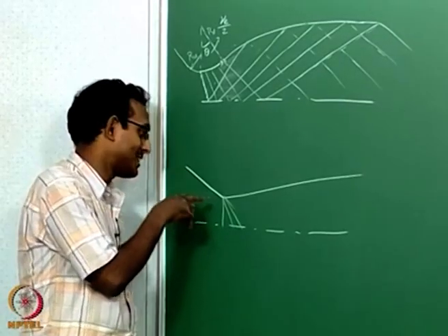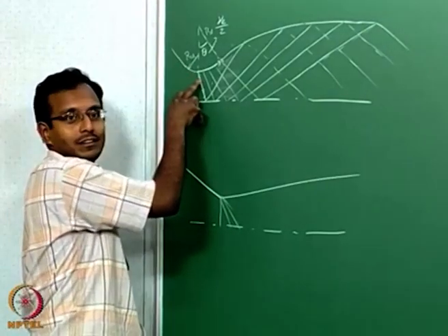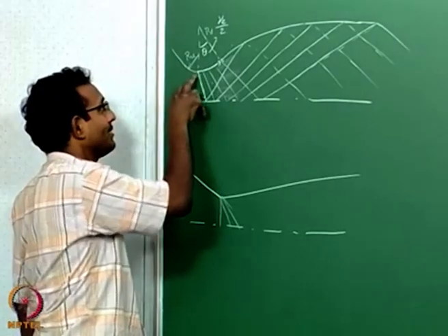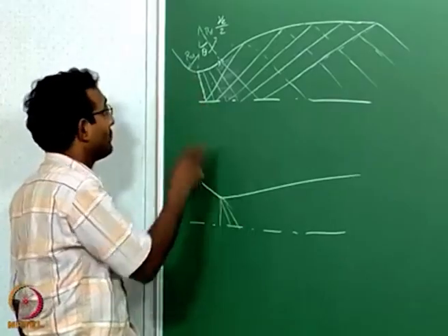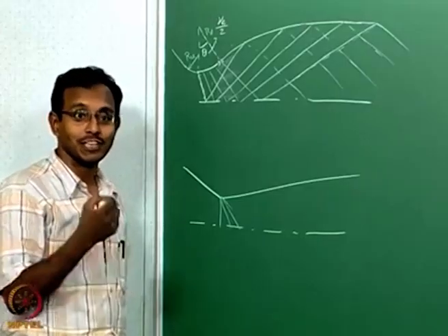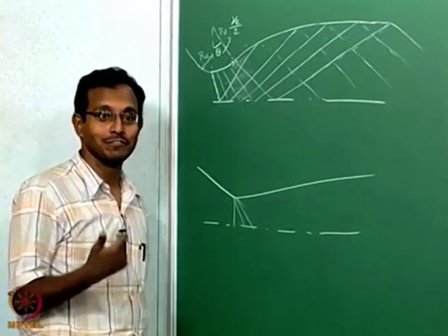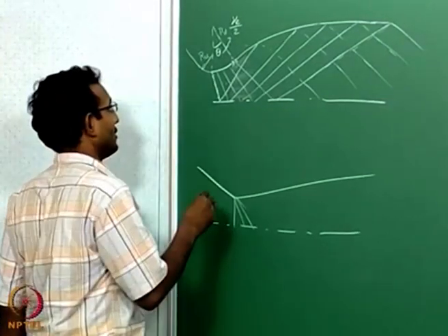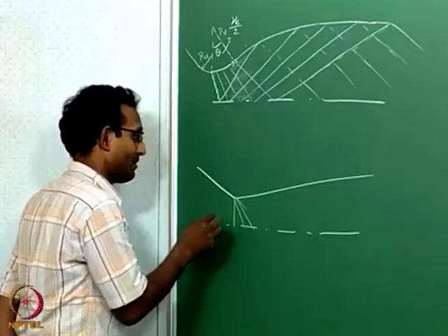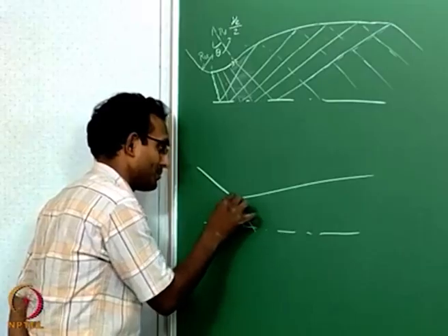I do not have any theoretical analysis for R. In this case you have a radius upstream here, that radius upstream we will use in our transonic flow analytical expression, and I will get our initial line here. But now if Ru equal to 0, I do not have any way of calculating that analytically, because it is a sharp corner. Sharp corners typically analytically it will go to infinity, things do not work very well, curvature is infinite, things will go wrong, okay. Not curvature, radius is 0, okay. So things will start going wrong, and because of that we will not use that method, and I will have to think about using point expansion.